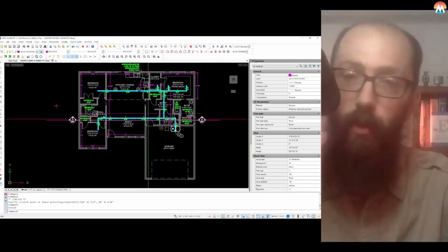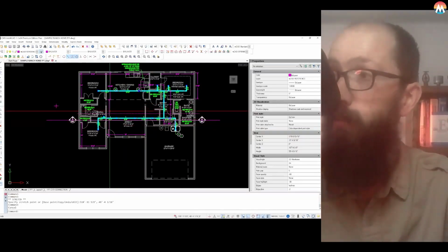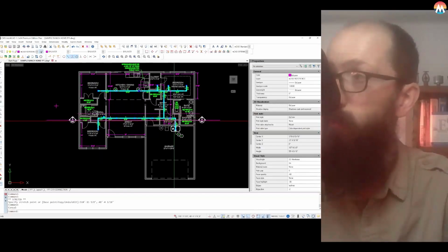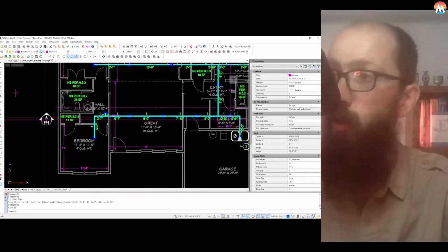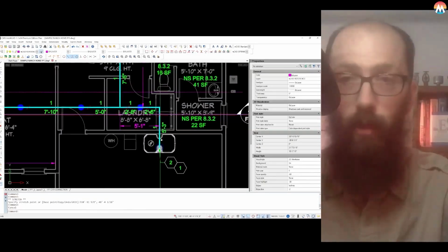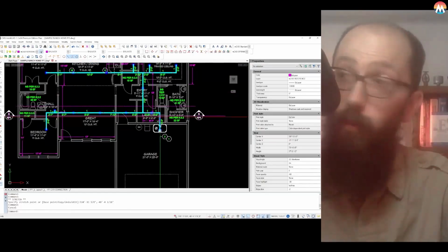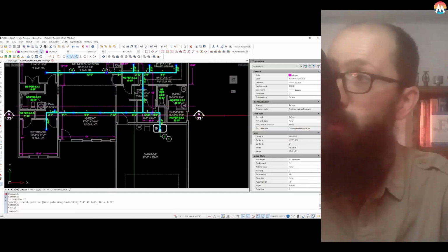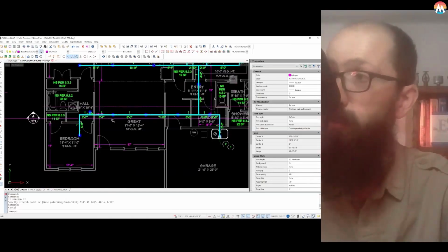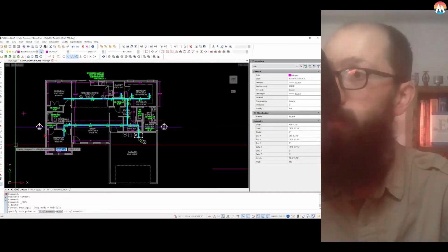Generally we show it so it would be back clipped, so you're only seeing either exactly where the line is, what's going on right where this crosses. Like if we were going to show only where this line crossed, we would show that pipe crossing it and that pipe crossing it, and that's nothing else. But what we would like to show is all of this piping, because that's a lot of good information. So if we imagine, let me just draw a line, or I'm just going to copy this one.